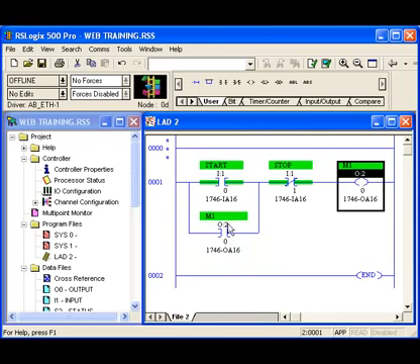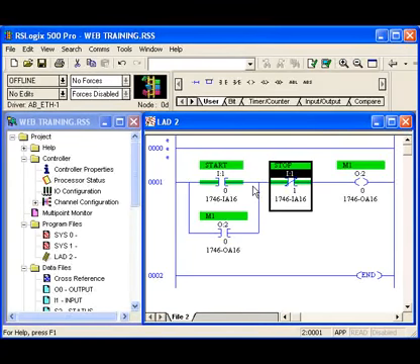What we have here is the exact same address as that output. Now the nice thing and the big plus with PLCs, and the big reason they were used when they first started, was that to take the place of many different relays, we want to be able to do a lot of this stuff internally. You could have a bunch of different internal coils and internal contacts. I could have 100 of these contacts if I wanted to in my program.